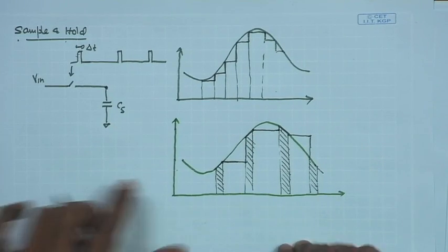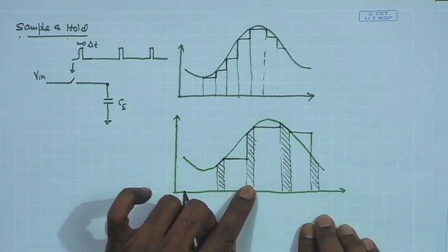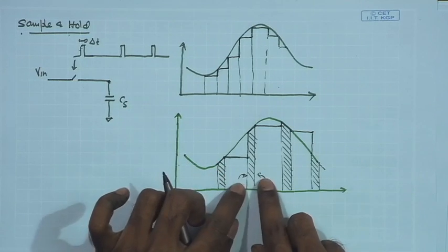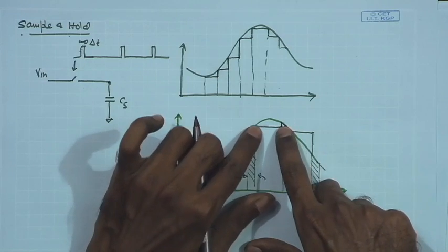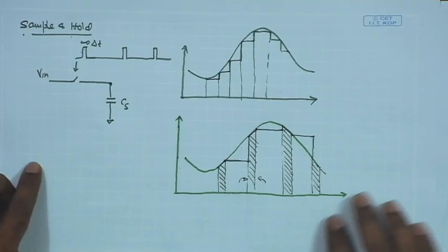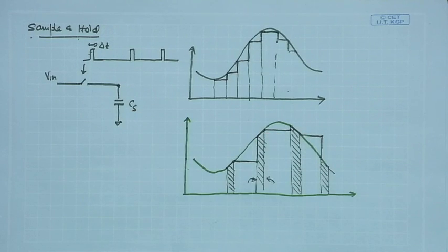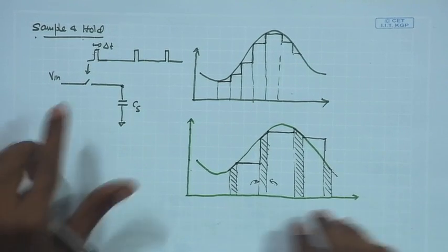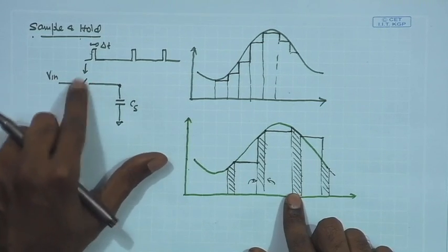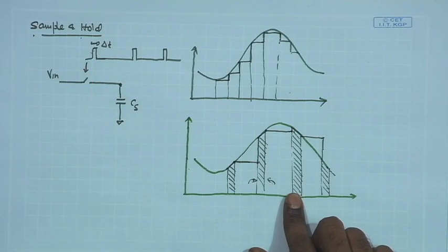Of course, if we want this entire sampling duration to be allocated to the digitization process, we would like to reduce this as much as possible. We would like to reduce the t on as much as possible, so that the A to D converter can utilize the maximum of this sampling duration in conversion of the analog signal into the digital value. So, it will be favorable to minimize it as much as possible, and also that minimization would require certain design consideration with the switch, what kind of sizing, what kind of transistor configuration we are choosing for the switch.